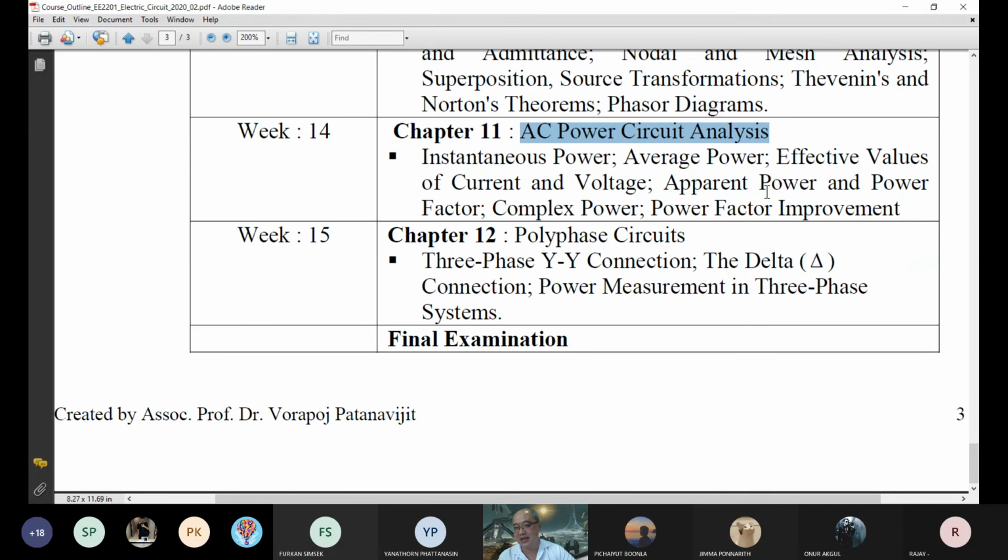If you would like to determine the instantaneous power or the average power in the time domain, you determine the instantaneous power from the transient circuit analysis and integrate it over a certain time. Or if the source is a sinusoidal waveform, you may convert the source and the load to phasor and impedance form, and determine the average power by applying the real part of the complex number.